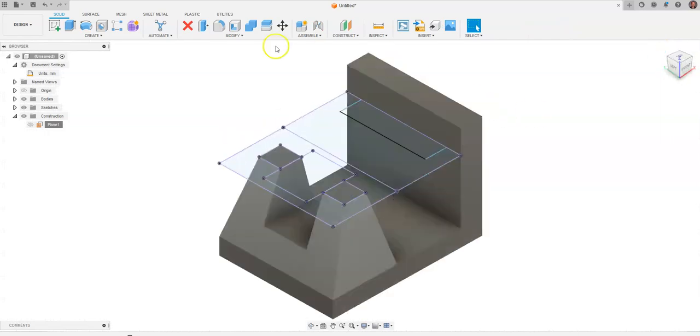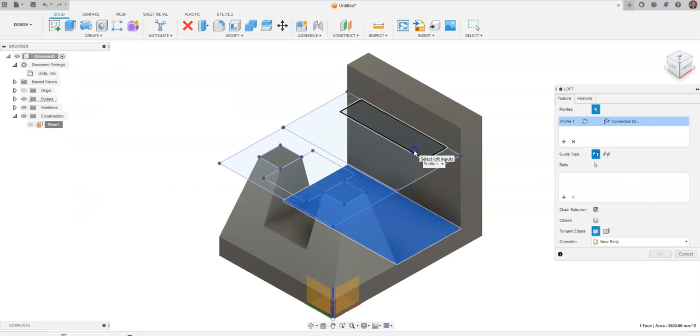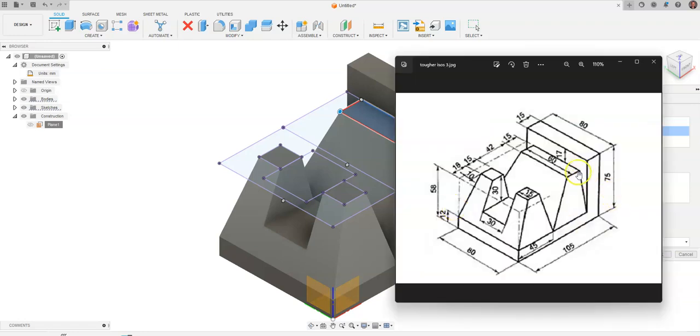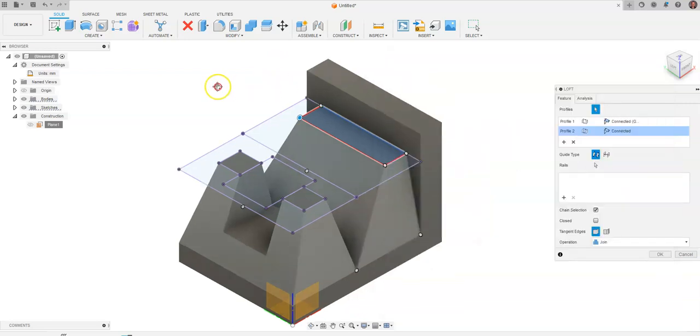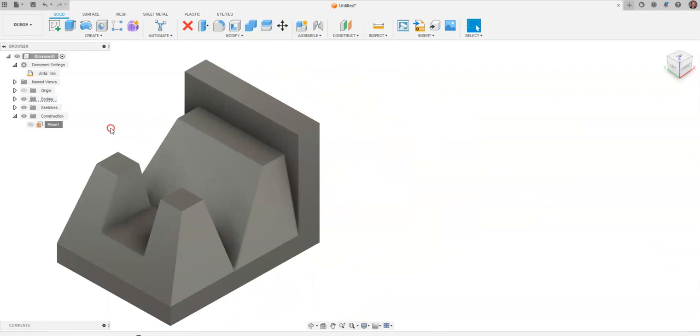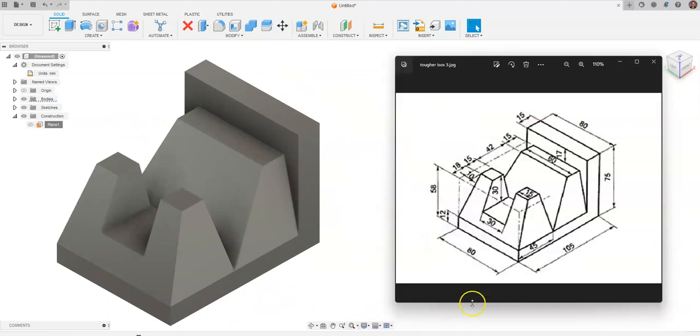Let's come up here. Let's grab a hold of our Loft command. This surface up to here. We have ourselves our little angle. It's neat. It wasn't off the back. It was the way I looked at this. It did look like it was coming off the back, but all I see is just the angled line here. Worked out well. We're going to go ahead and come back. We'll say OK. We now perfectly have our object.